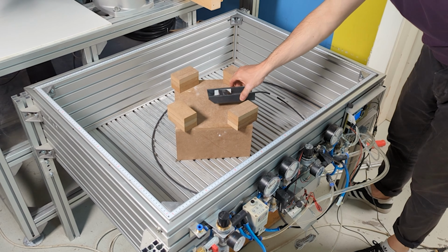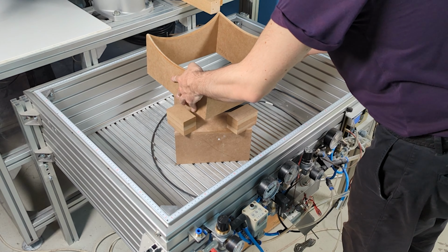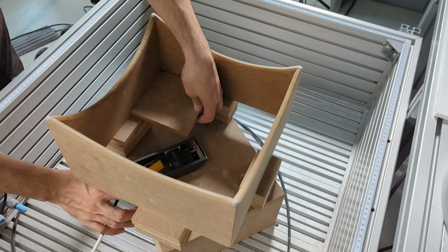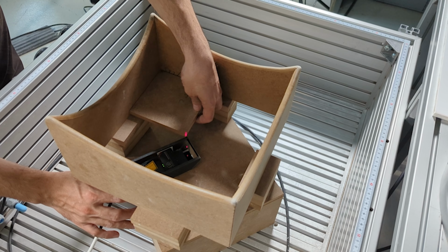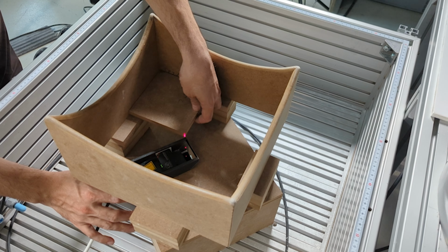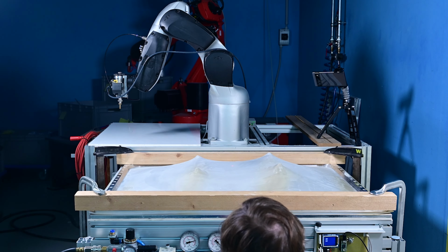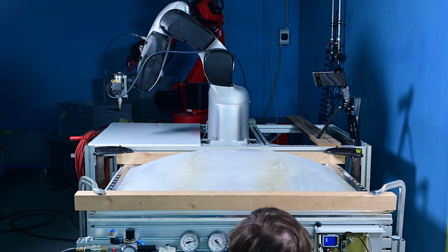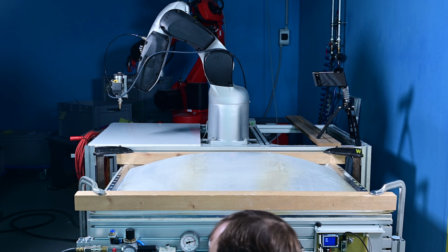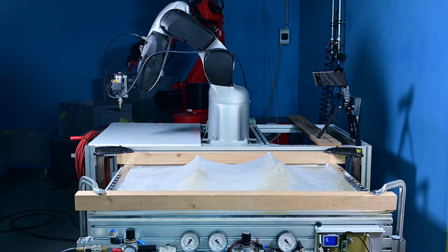The actual molding process begins by positioning a support frame and laser distance sensor inside the machine. This sensor is used to control the membrane deflation process. Next, the membrane is installed. After initial inflation to avoid uneven prestress, the desired deflation is set at the digital controller, and the pressure in the machine body is lowered. Once the pre-programmed deflation is reached, the controller keeps the pressure inside the machine constant, and the mold is ready